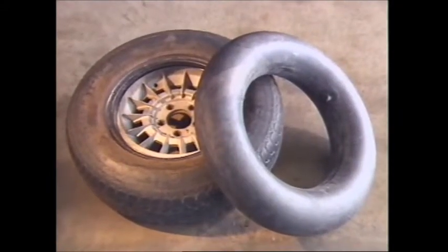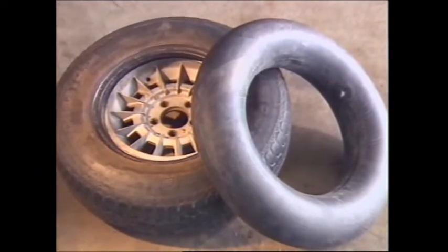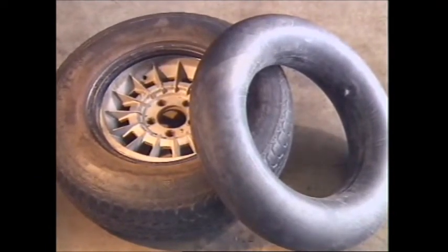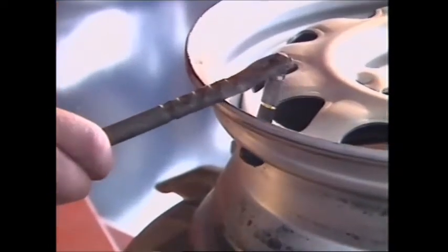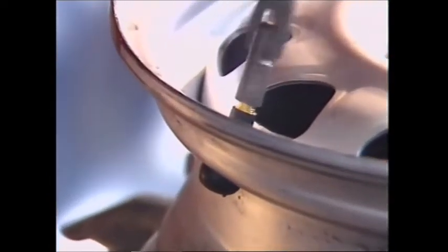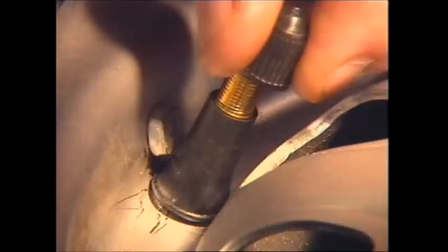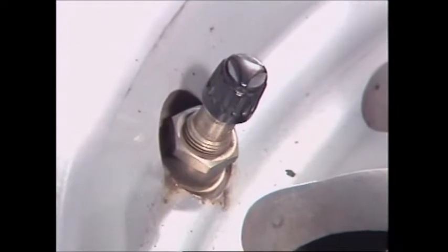A tube-type tyre uses an inner tube which provides an airtight container inside the tyre. A tubeless tyre is lined with a soft rubber layer to form an airtight seal. This inner liner also seals against small penetrations, letting air escape only relatively slowly. When a tubeless tyre is fitted, an airtight valve assembly is used. It can be a tight fit into the rim or be held with a nut and sealing washers.